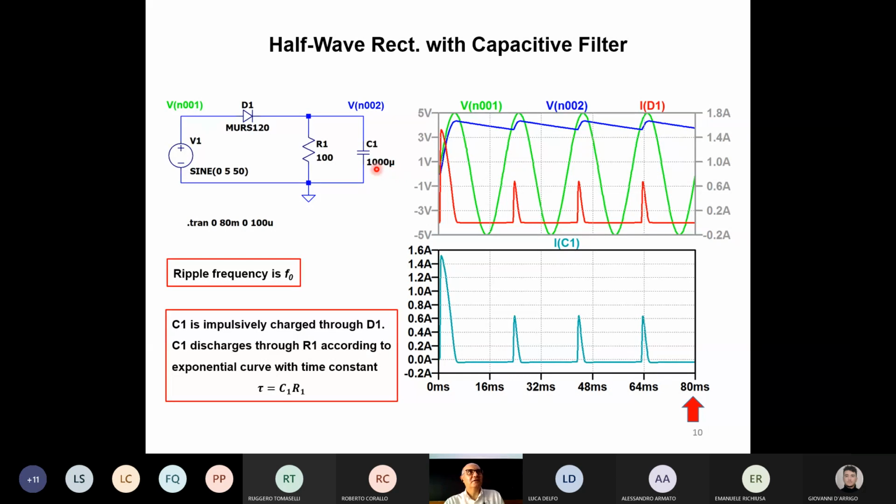This is the simulator. It knows that capacitances are in farad, so it doesn't put microfarad, it just puts micro. The same as the resistance. You will never see 100 ohms. It's useless. Resistors are in ohms, so it just says 100.